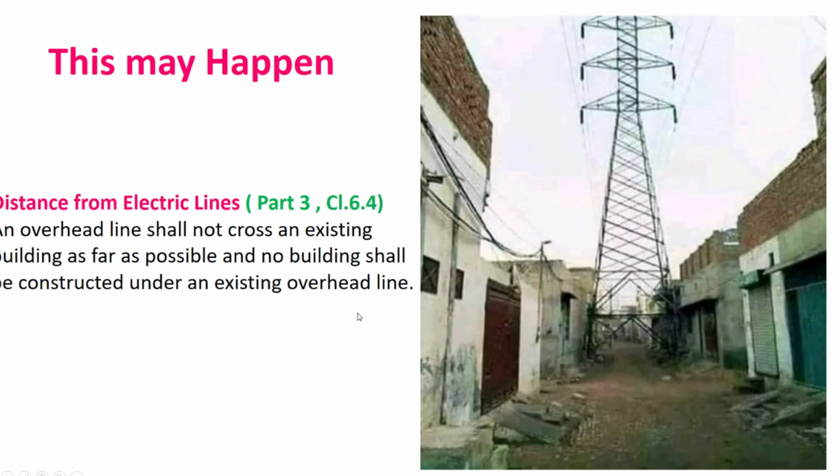In fine sands and silt, penetration below the zone on which trouble may be expected from the frost. Now in India normally this is not there for the frost. Or the maximum depth of the scour, wherever relevant, should be considered. Now suppose you are having a building, you have any type of a stream or a nala just near to it, then it should go below the depth of the scour of that particular water stream.